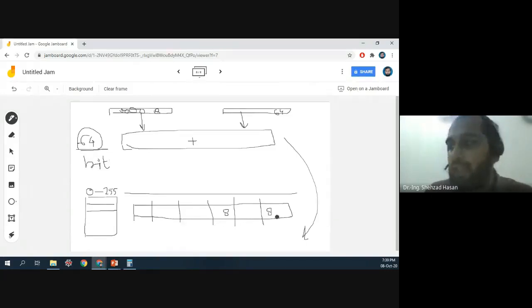So what we are saying is that normally in a ripple carry adder you have ripple effects going on through the whole adder. In this case, we are not going to propagate the carry after every 8 bits. So this is not going to happen, and this is also not going to happen. Within these 8 bits there are going to be carry chains, but not in these.